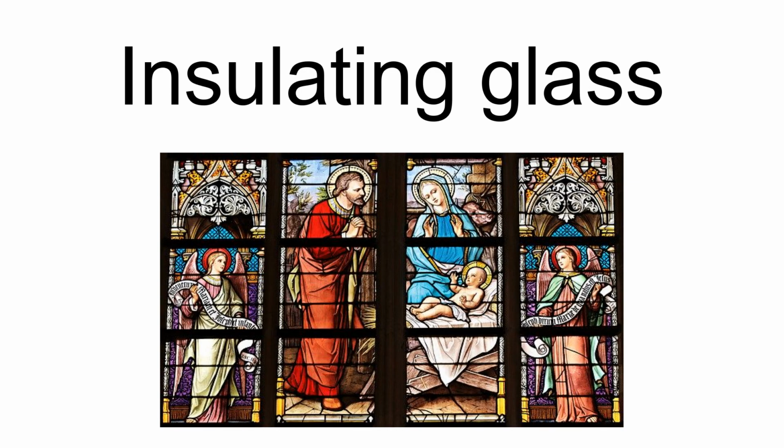Insulating glass, or double glazing, consists of a window or glazing element of 2 or more layers of glazing separated by a spacer along the edge and sealed to create a dead air space between the layers. This type of glazing has functions of thermal insulation and noise reduction. When the space is filled with an inert gas, it is part of energy conservation sustainable architecture designed for low-energy